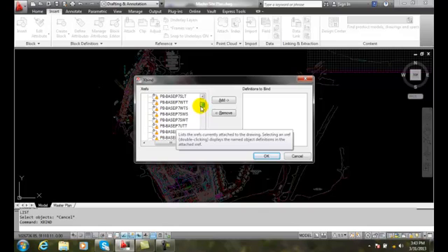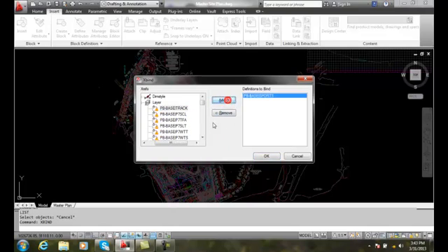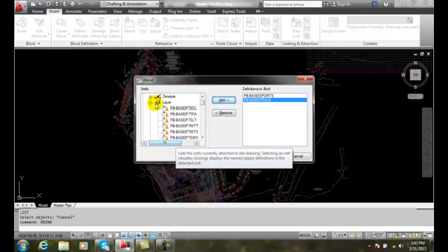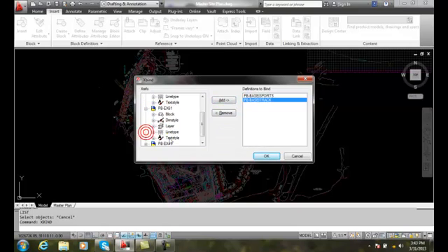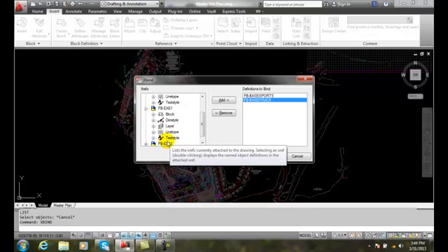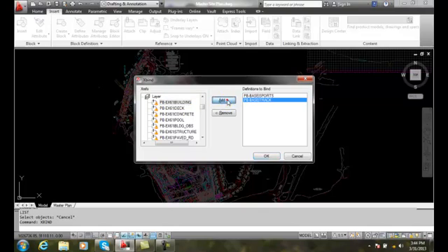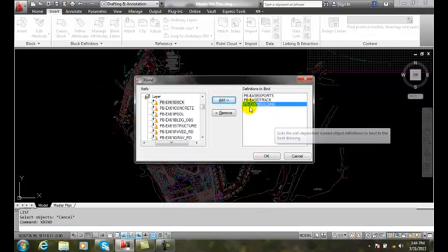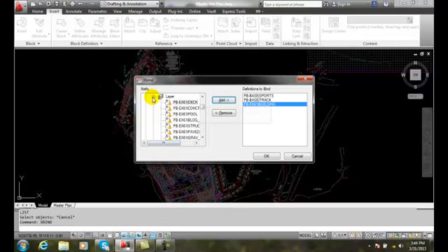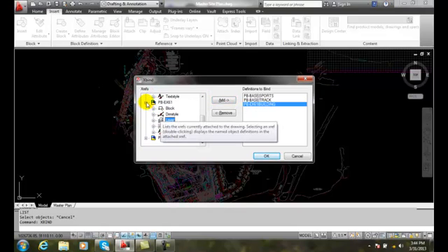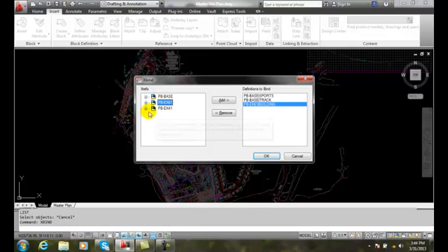Okay. So if I just wanted the sports and the track in, all I do is highlight that and say add. And I can say I wanted the track as well. Now I can jump over to my existing 61, and I can go to my layers here, and I can say I wanted the buildings to go in there too. I can add that in. And so I can just define whatever it is I want without having to bring in the entire XReference in.